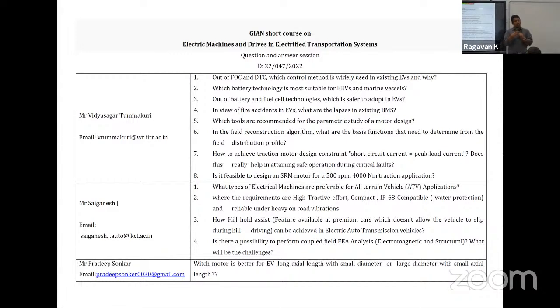That's a very general rule of thumb that we normally follow. Axial machine is the opposite. When you want more torque, OD goes up. So if you want a machine with a very high starting torque, you want as much diameter as you can get. But there are very hard constraints. The thing about EVs is that oftentimes you're limited more on the diameter than on the stack length, depending on whether you have a differential or not.